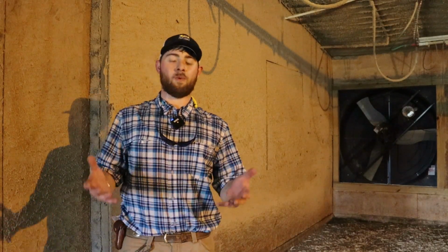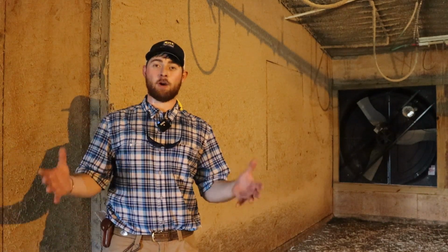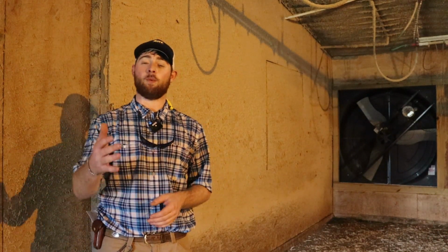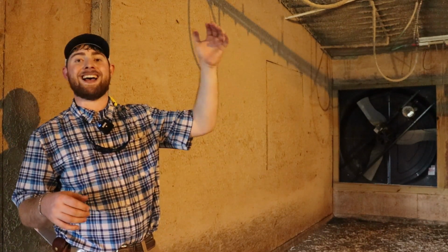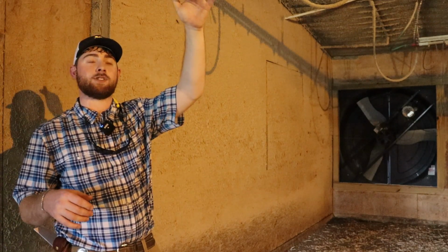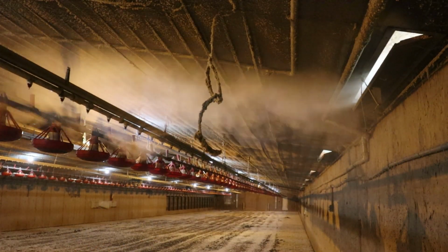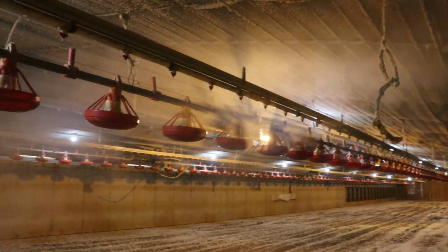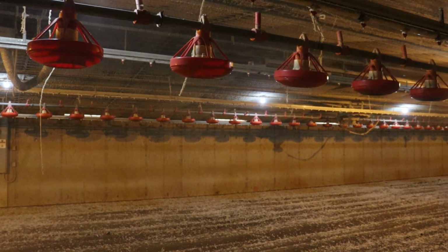And that brings us to why poultry house tightness is important, right? It takes a lot of money to build these structures that we have, and we want to make sure the air is entering where we design the air to enter. That's because we want to take advantage of some of the heat that's on top of our ceiling. Most of our sidewall style inlets are designed to shoot the air across our ceiling before it falls to the ground. Two reasons for this: we're taking advantage of some of that hot air that's up at the ceiling to heat the air, and it takes longer for the air to hit the floor, giving us more time to heat the air.